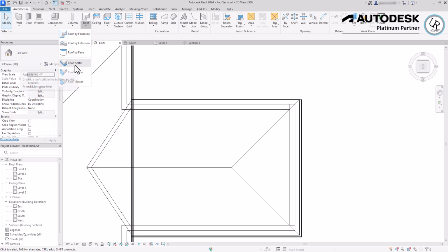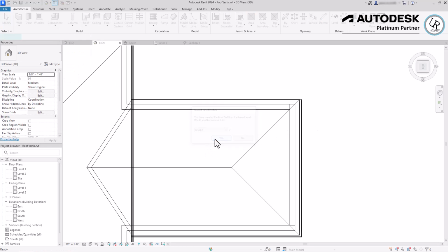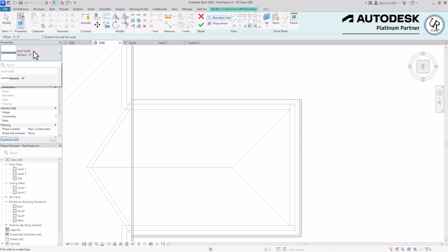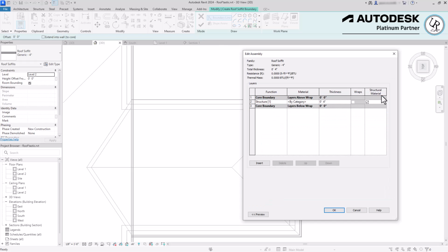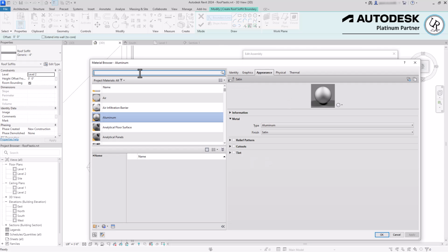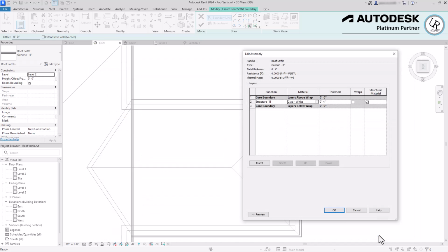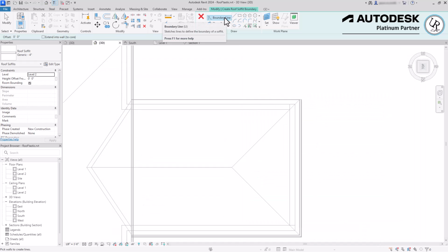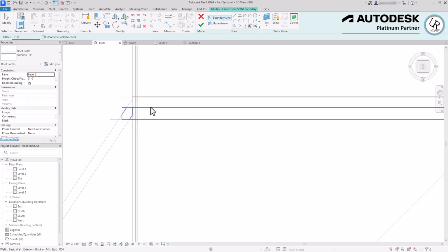Roof drop-down list and choose soffit, not fascia. And I'll associate that with level 2. And you can choose your soffit thickness. Also choose a white clad for that. And with this one, you actually build the extent in a plan view orientation of where you want the soffit to exist. Use the pick line tool, the pick wall tool, and define a 1 foot offset.